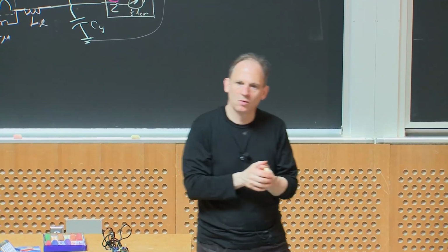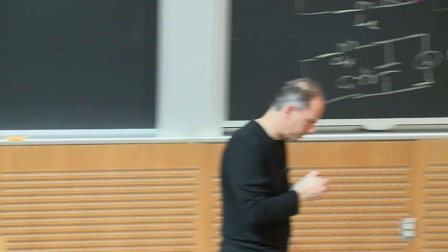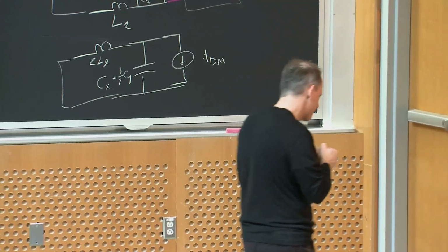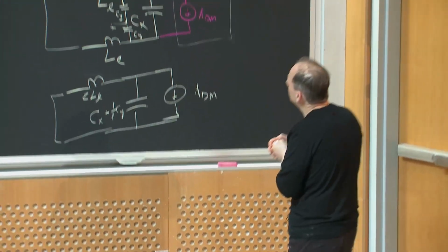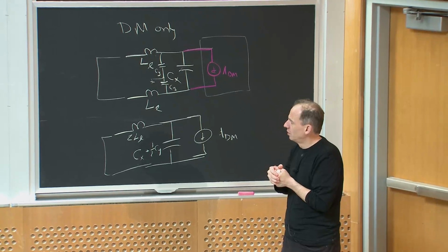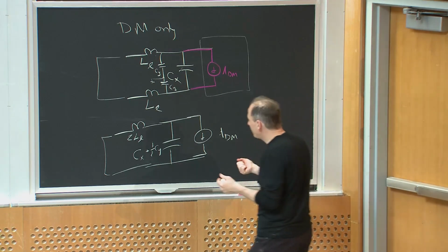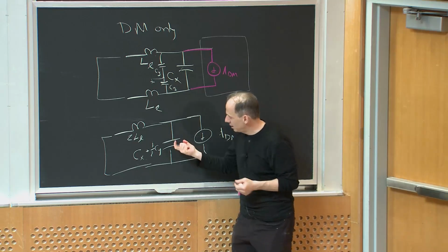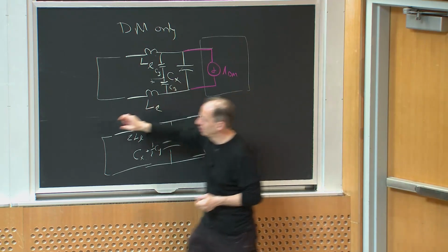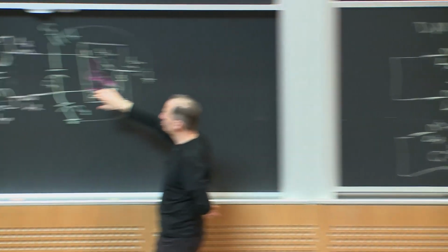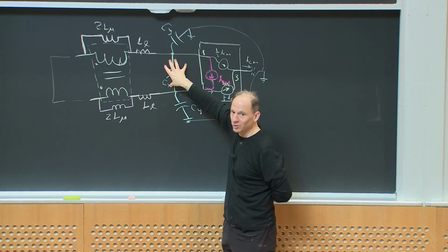So what do I want to know when I'm designing a filter, right? If my problem is common mode noise, beefing up the X capacitor here is going to do zippo, right? Because the common mode current doesn't even flow through that. It's a virtual open.